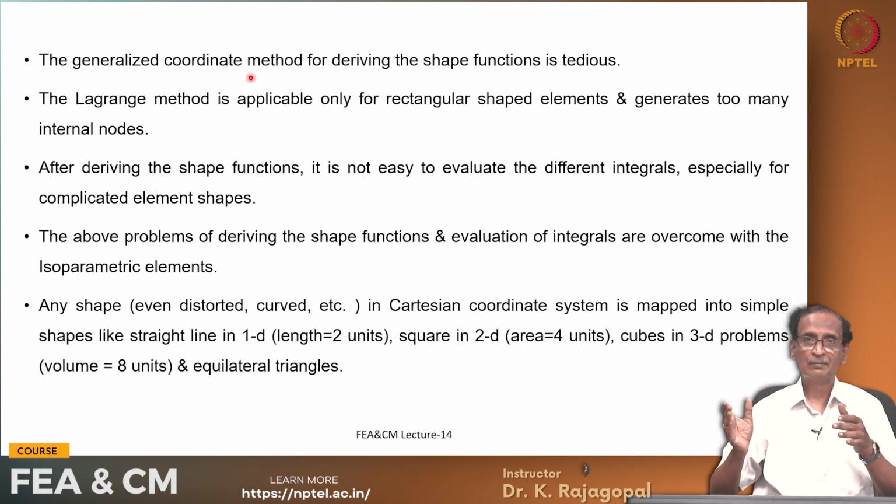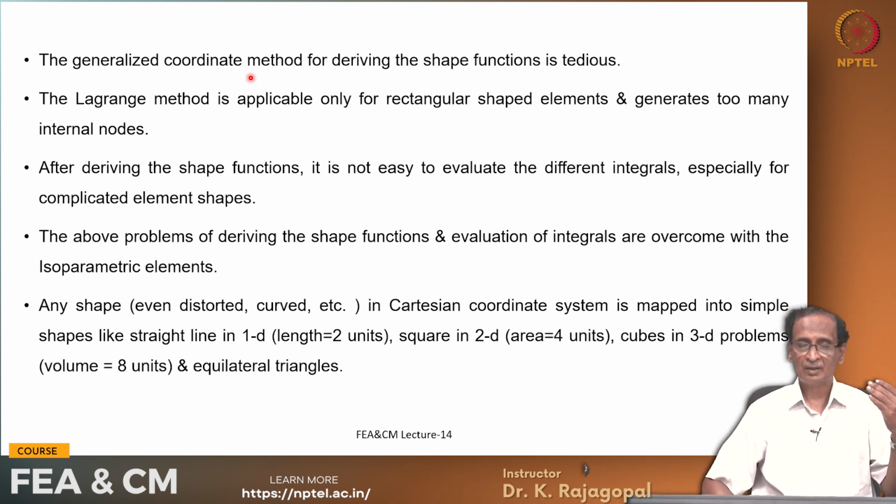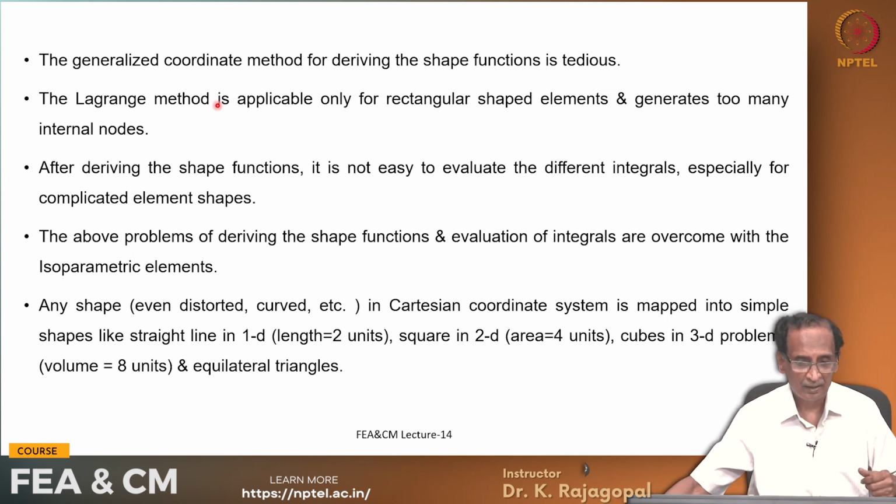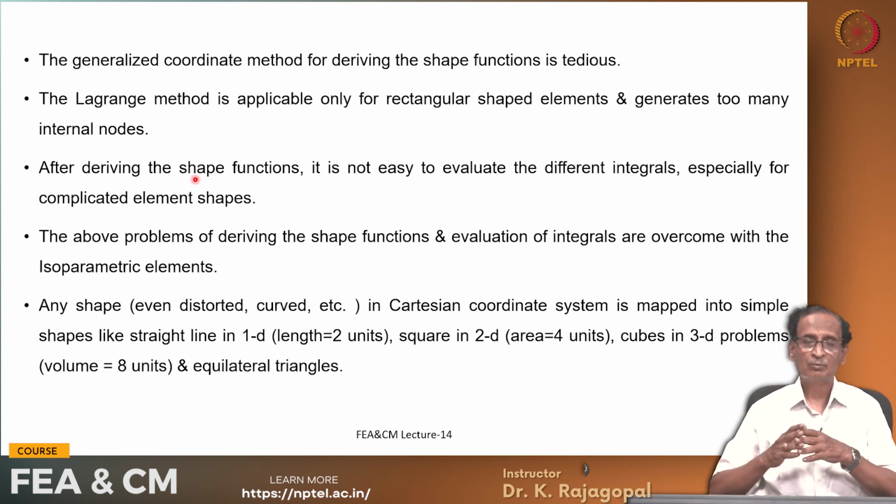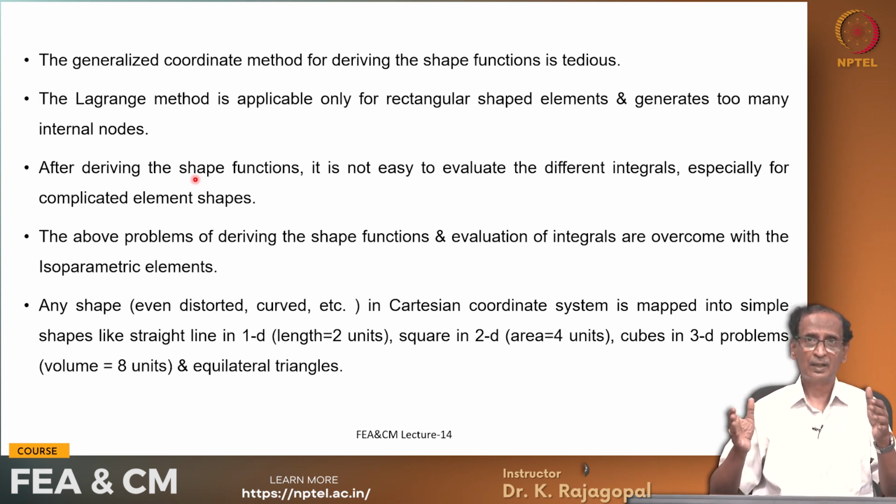in some quantities with polynomials, and we end up with a lot of integrals, whether it is stiffness matrix, the load vector due to the self weight, or due to the initial stresses and so on. And so we need some method for evaluating them, and when we have irregular shaped elements, we cannot directly do the computations because we do not know exactly how to do the integrations.